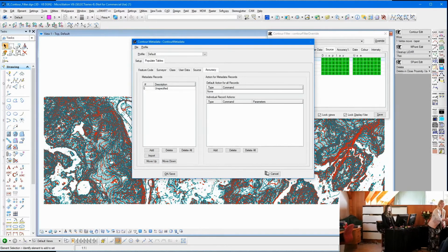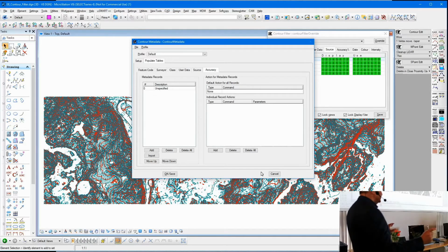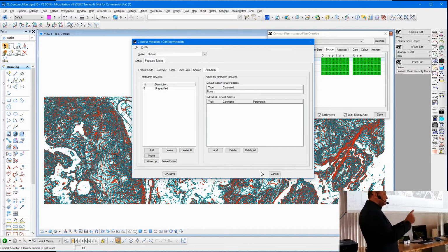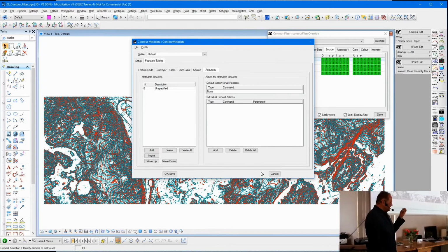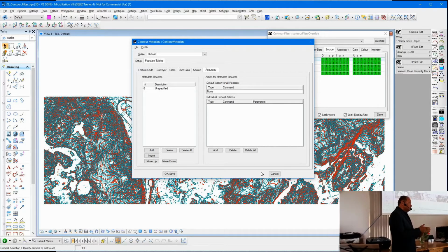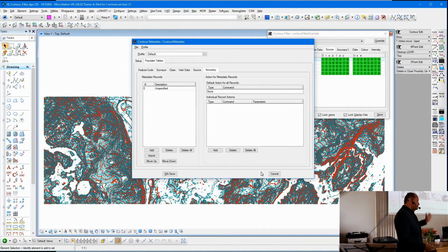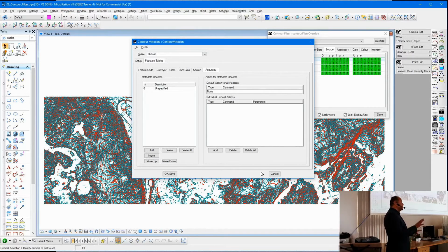Yeah. So you can combine your accuracy with your data source. You could say, okay, this is LiDAR data at that particular accuracy. Show me only that. Show me only LiDAR data at a particular accuracy. On endpoints, you would get that type of thing. In other words, your mass points, what we call endpoints. If you've contoured and you want to knock it through to contours, then you're free to carry on and use that same naming convention throughout in your contours as well. But you can define them separately.